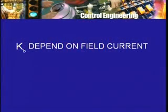For a given motor, with a given field current, or the field current is also referred to sometimes as the excitation, and that's why the motor was called separately excited motor, that it gets its field current from a separate source of supply. This KB will depend on the field current, of course.